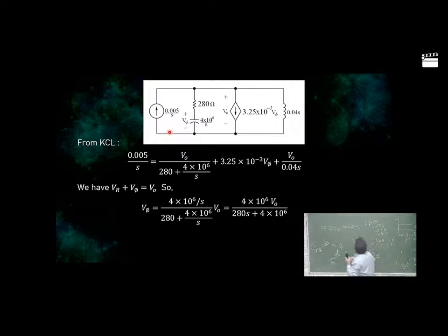Voltage division rule is that if you have a voltage source here and you have two resistors R1 and R2, then VR1 will be given by V into R1. Voltage across that resistor is given by V into that resistance by the sum of the resistances, R1 plus R2. Okay. Similarly, you have the current division rule for parallel circuits. This is a current source I, R1, R2.